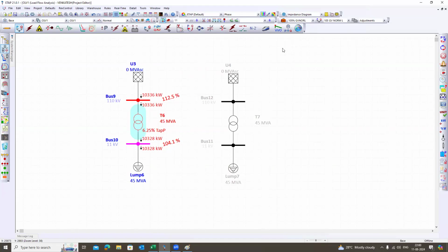Okay, so how to set the intermediate taps? This is an upper limit and lower limit. So what about the intermediate taps? Is there any condition or specific guideline for that? Oh, no, it's not like there are specific guidelines. Generally, for the LV side voltage, we give 2.5% for each tap variation. That might depend on the utility.